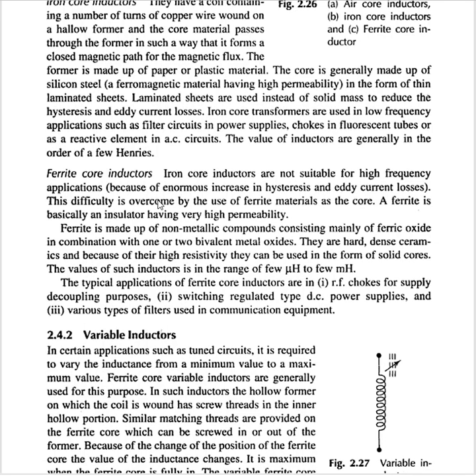Ferrite core inductors: iron core inductors are not suitable for high frequency applications. This difficulty is overcome by the use of ferrite material as the core. A ferrite is basically an insulator having very high permeability. Ferrite is made up of non-metallic compounds consisting mainly of ferric oxide in combination with one or two bivalent metal oxides. They are hard, dense ceramics, and because of their high resistivity, they can be used in the form of solid cores. The value of such inductors is in the range of few microhenry to few millihenry.